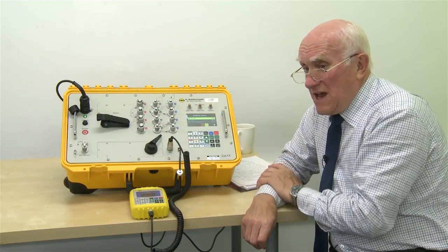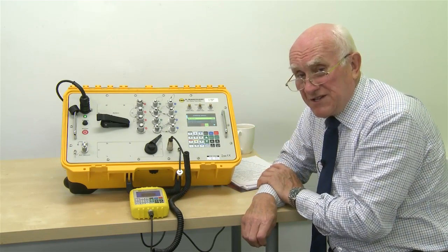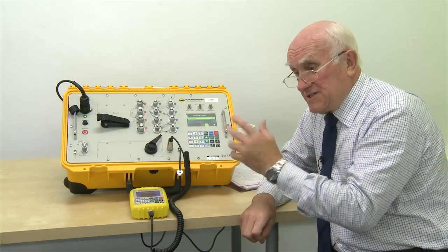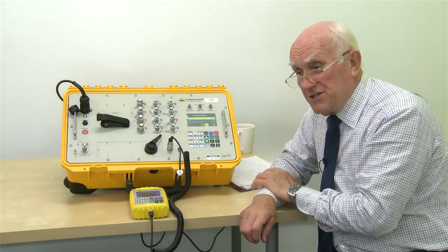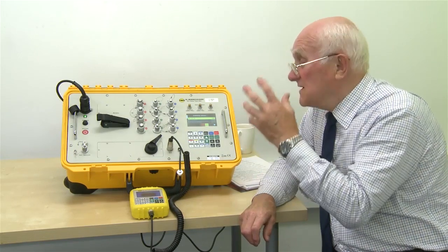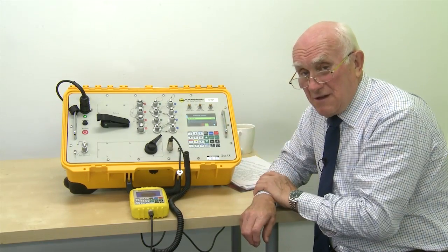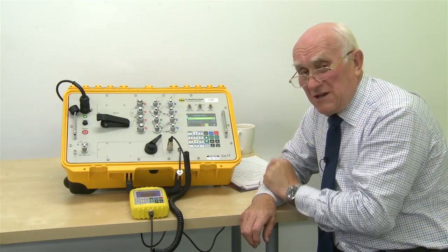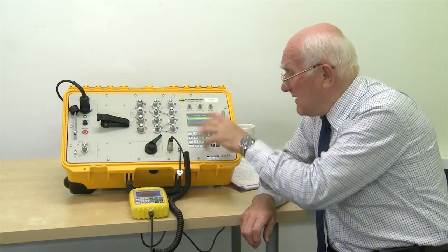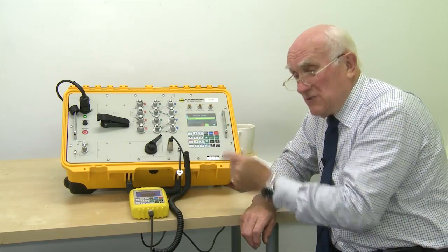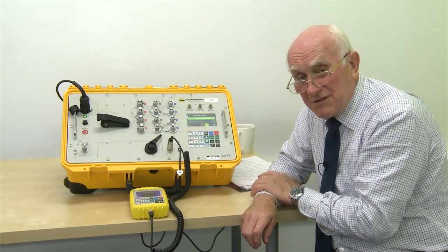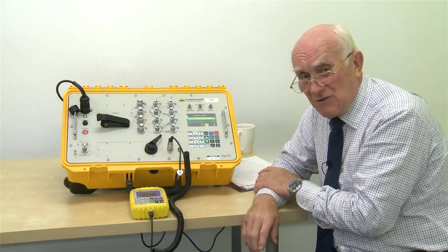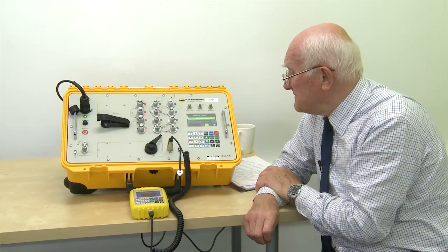when you switch the instrument off at the end of your testing, those limits you've just entered will be forgotten, and next time you start up you will have the situation where the previous factory fitted limits apply. You can change them permanently if you wish, but we don't allow that via the front panel. It tells you how to do it in the calibration manual, because that we feel is a different supervisory level to do that type of exercise.